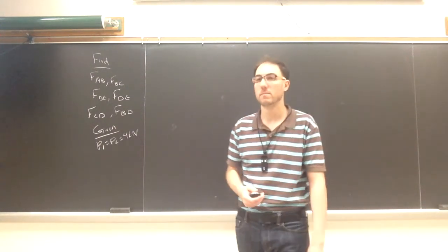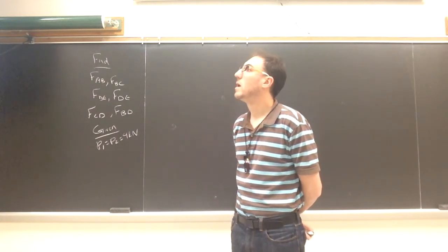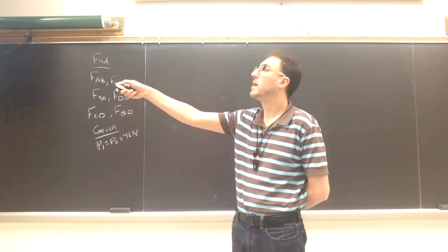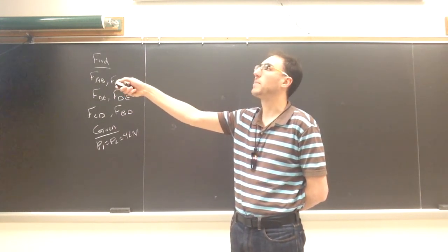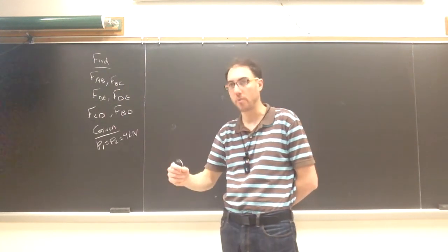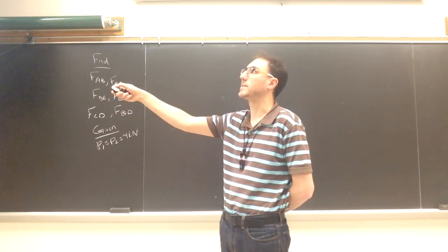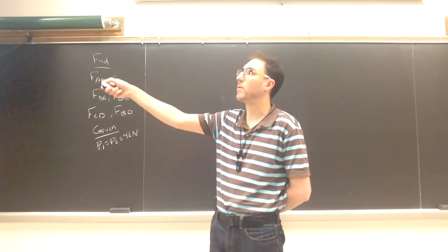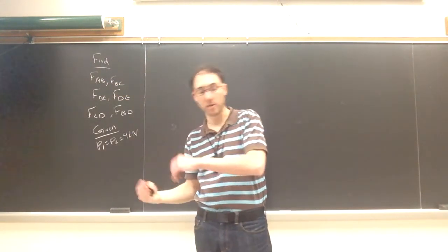Looking at that, how do we know BE is orthogonal to ABC? In this case, if this is 30, then by the geometry, I believe it's orthogonal. It actually wouldn't have to be orthogonal as long as a component of it is orthogonal to AC. So it might not be the case that AB and BE are 90 degrees apart. But as long as it has any component in this direction, then it would be a zero force member.